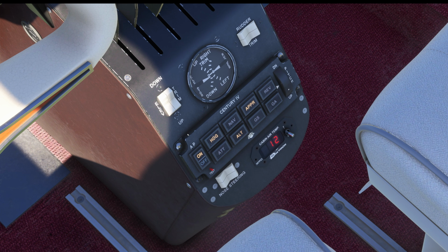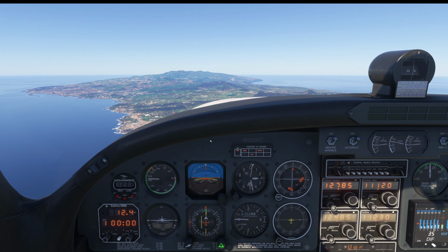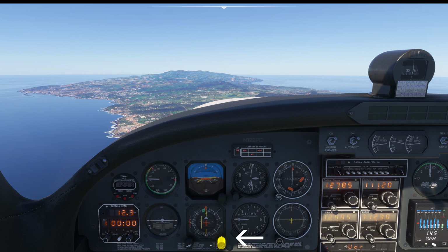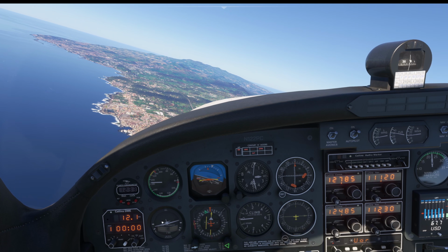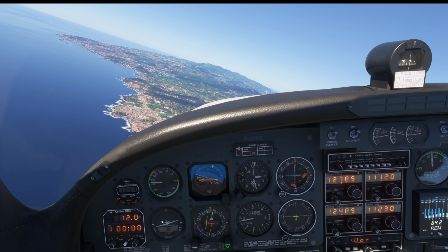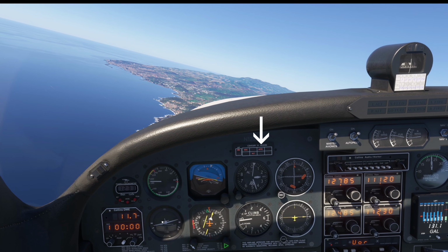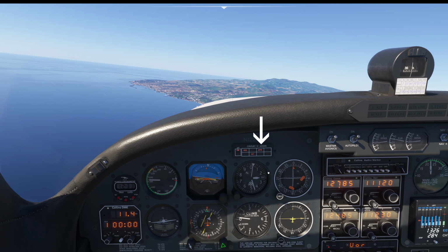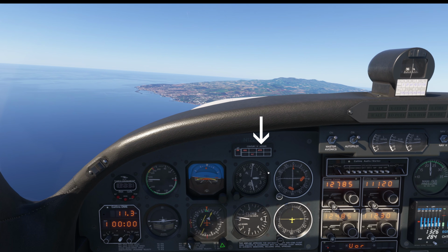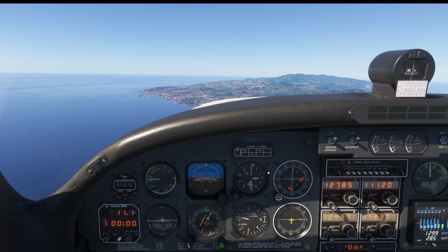Both heading and approach buttons will light. In this state, you can steer the aircraft with heading bug and set a shallower intercept angle. The approach mode remains armed, and it will activate when CDI needle comes closer than 50% deflection. From there, it will work just like a standard approach.